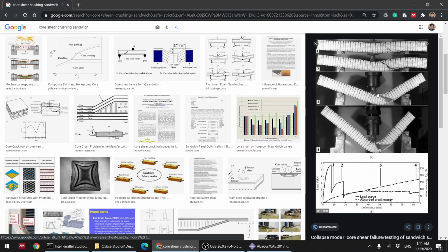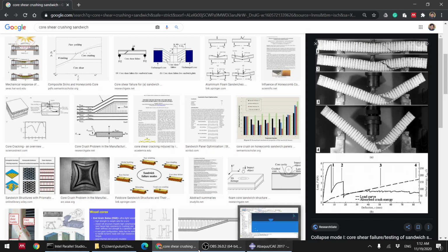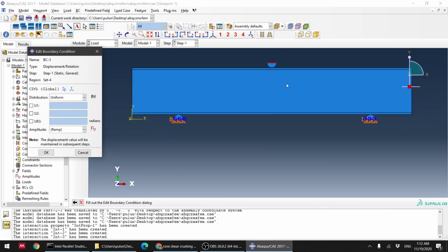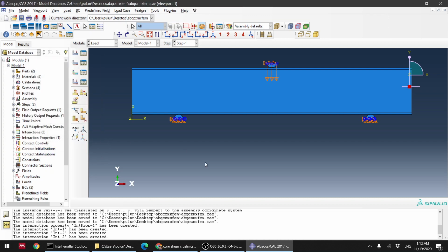You see that it moves around the thickness. I mean, this indenter moves from here to here, so it basically travels through the thickness of this part. We made it 50 before, right? So make it 50, guys. I think minus 50, because it should go down. Okay, nice.